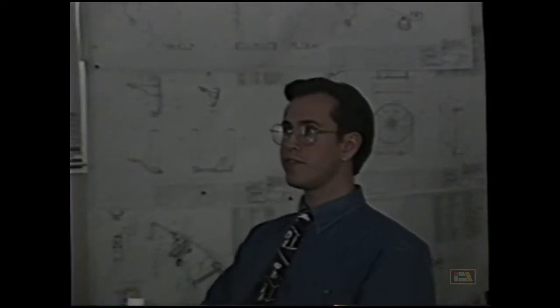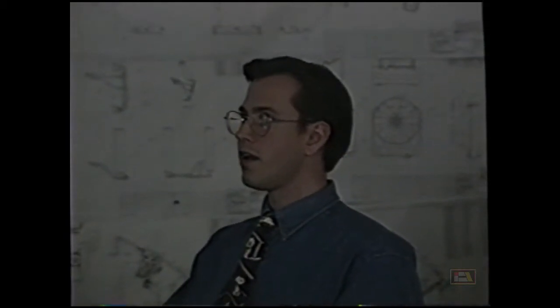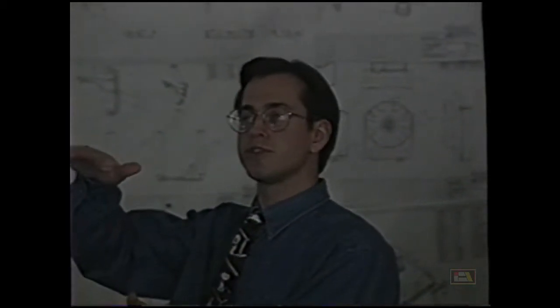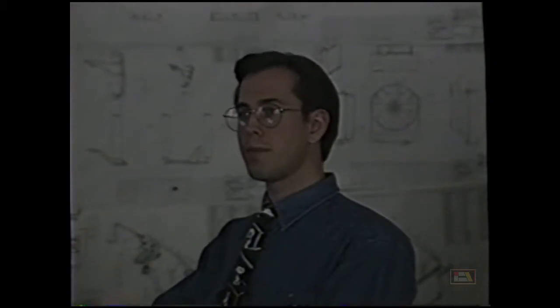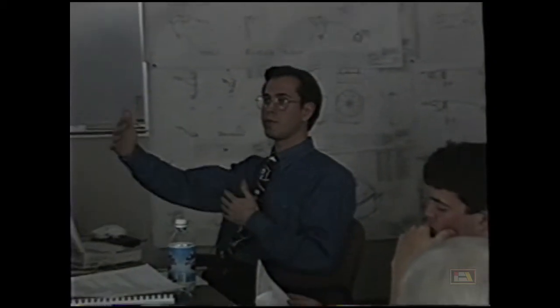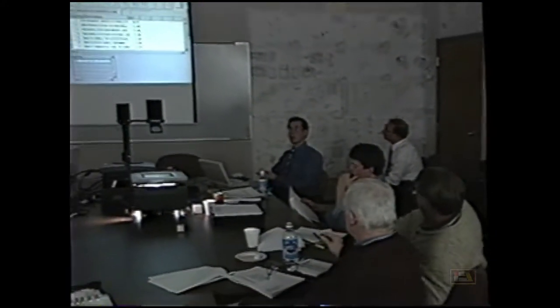So I think what Betsy's done in that case is she's said the operation's 28 minutes worth of work, but she's made a 2-man assignment. Because the work's being done in parallel, 28 divided by 2 is 14, so you know that you got a good flow. So depending on the situation, we're able to come up with some workarounds, but that's one that I can come up with for the cab line. We had 28 minutes worth of work, but we have 2 stations doing it in parallel, so that would be a case where we made it a 2-man assignment.